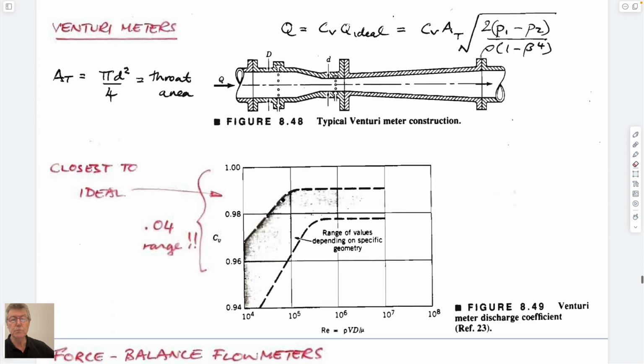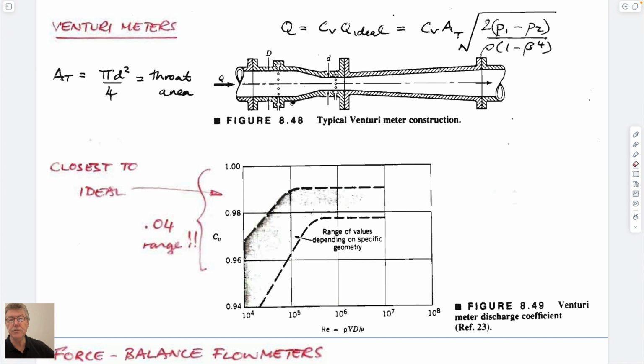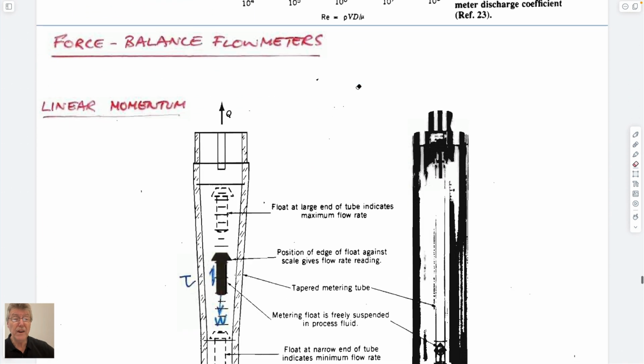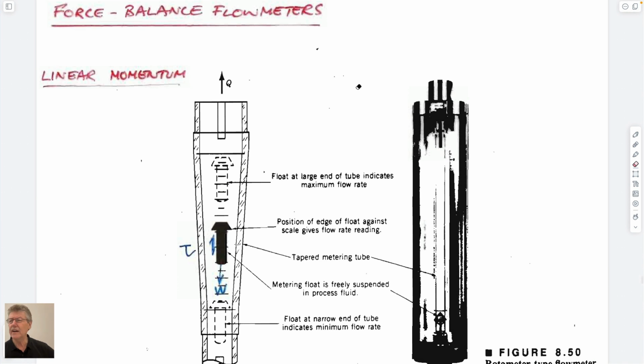And the most smooth transitions, of course, are Venturi meters, which are just a very smooth narrowing of the flow before it goes downstream. Other ways of doing this: I've never quite worked out how the mechanical tire gauges work. You put it in a tire, and it measures the pressure by a little stick that comes out. It may be related to this.